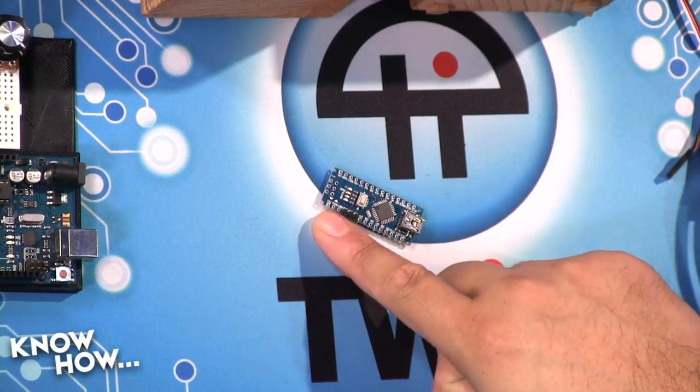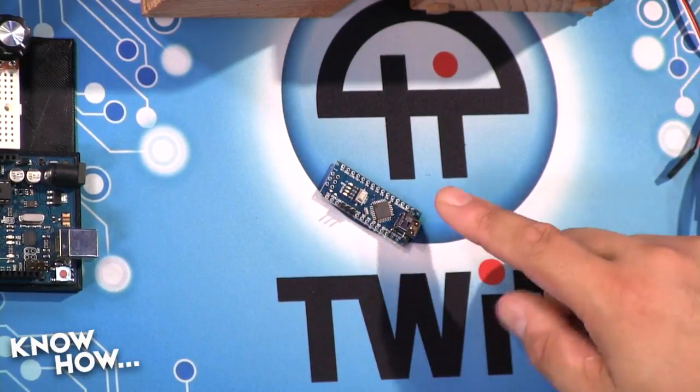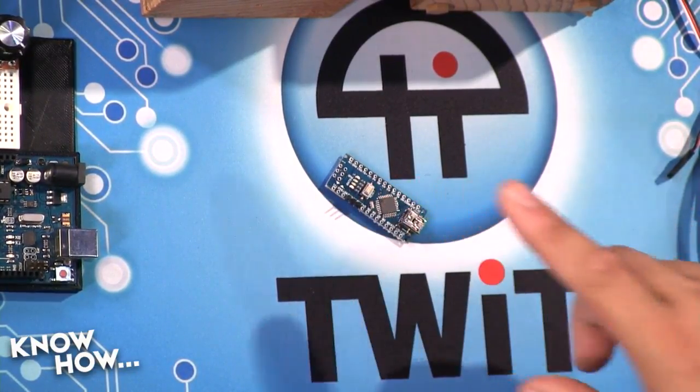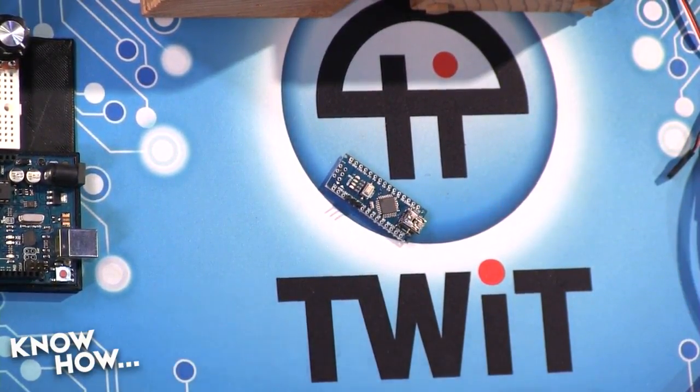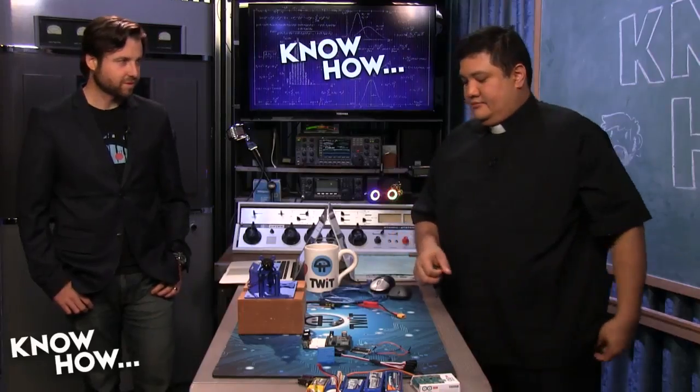In fact, this very Arduino Nano, if you go to the overhead, Alex, this is the one that we only soldered 3 pins. That little baby guy. That little baby guy, right. So what it did was it put the firmware on here to make this the bridge between the computer and the ESC, right, so that I could reverse rotation without having to resolder the wires. And not just that, but also fine-tune your ESCs. Precisely, yeah, reprogram it. But here's the thing, there's nothing that says I can only do that.